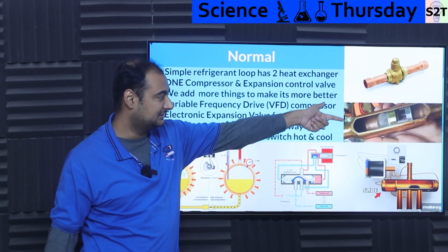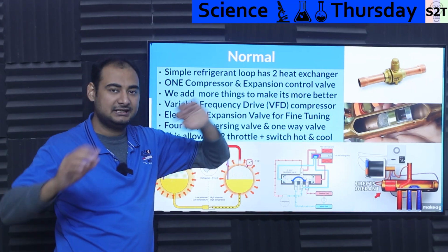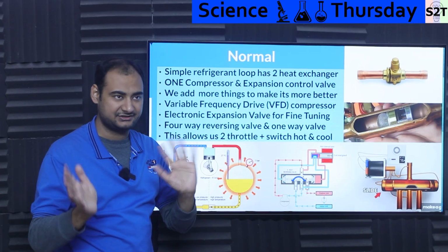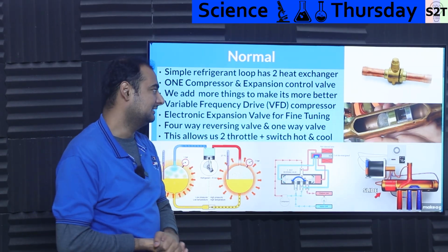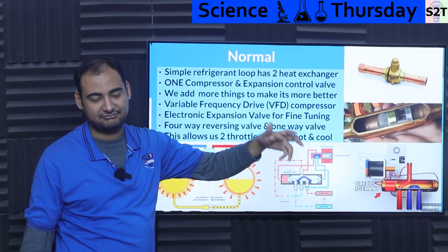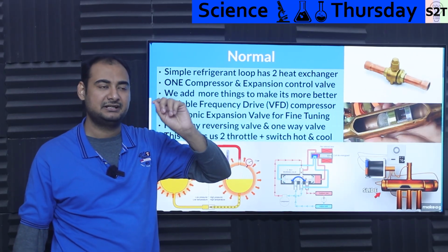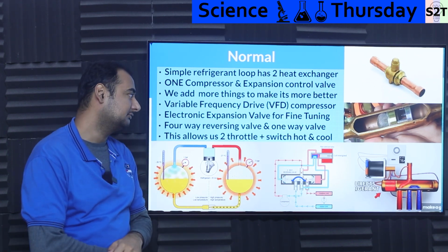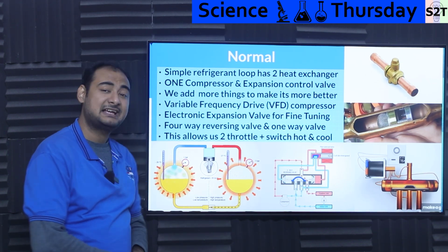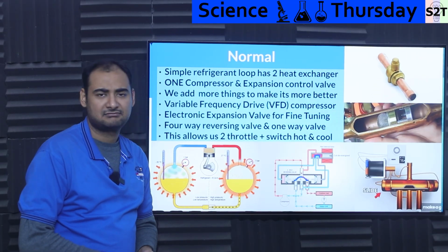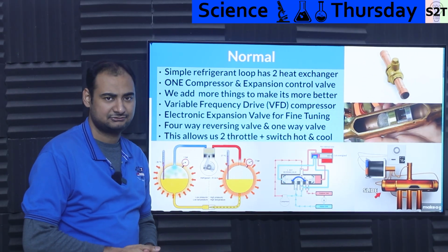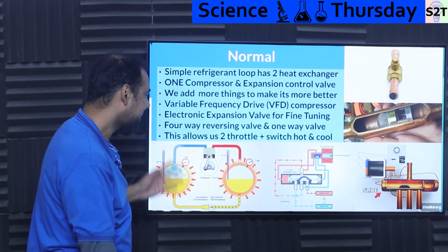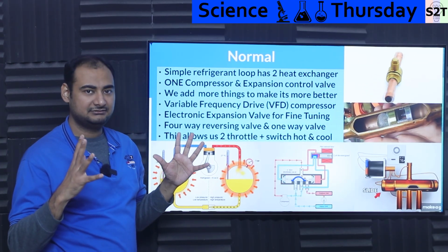So you have to have another check valve and then another expansion valve in the other direction, so it works in both directions. So you do have to add 3 things. One-way valve, and basically double one-way valves and double expansion valves, and this is what we call a 4-valve system. It does add parts to it, but all of these are rather simple devices, nothing fancy, nothing too complicated, and it does work. Like, heck, right now it's working. So it's a very elegant scenario.